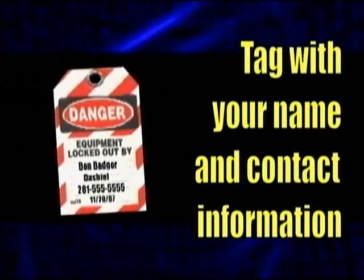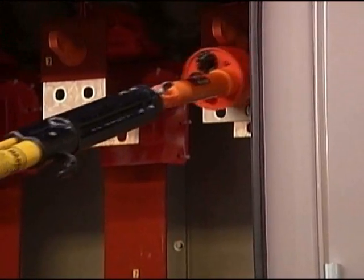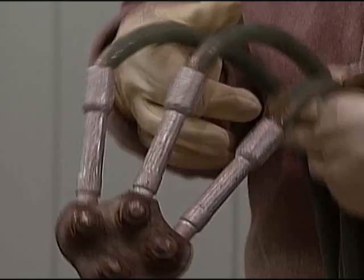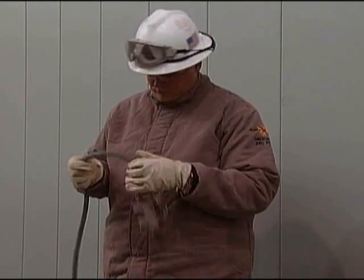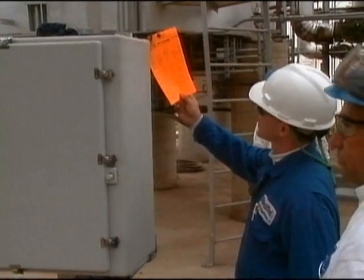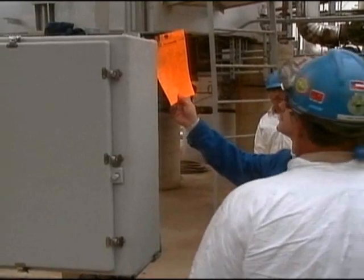Lock out the equipment with an appropriate lock and tag the lockout with your name and contact information. Check for voltage with the approved detectors or meters. Ground each phase using an insulated hot stick. Prior to using grounds, check the inspection tags and visually inspect for bad wires or bad connections. Finally, when you're certain the equipment is totally isolated, locked out, and grounded, work can be performed.